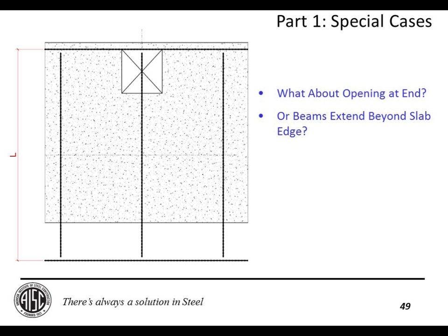Now you know as an engineer that this portion in the middle is going to do something. It's going to help you to some amount. But if you are designing this in a program, say RAM Steel or something like that, the second you have 1 millimeter of beam that sticks outside of a composite slab, it will say that beam is non-composite and you get no effect of the composite action at all, which is an excellent conservative approach.